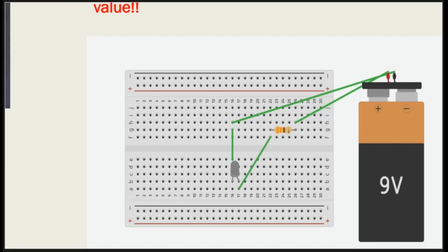Up. You go through the diode. Oh, sorry, the LED. And then you what? You get down here. Where do you go then? Straight up. All the way. Up. Back to the negative terminal. Okay? This is how you connect a breadboard. You never connect it diagonally. Impossible. Okay?